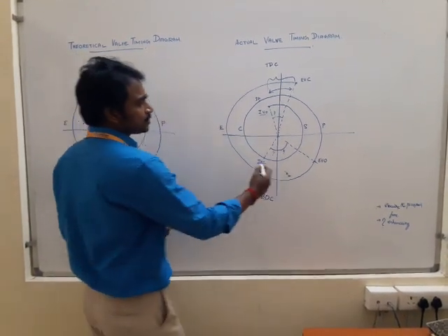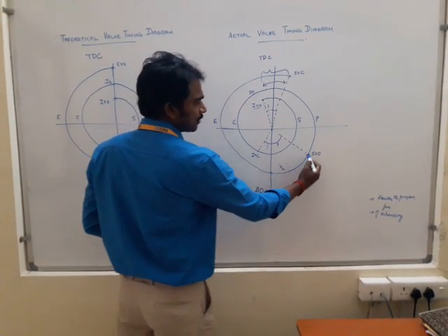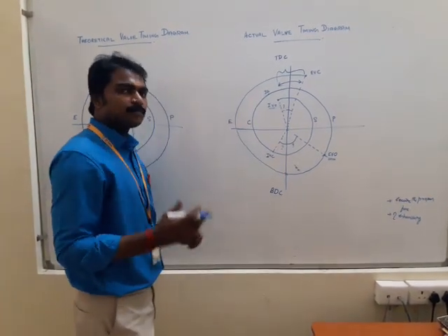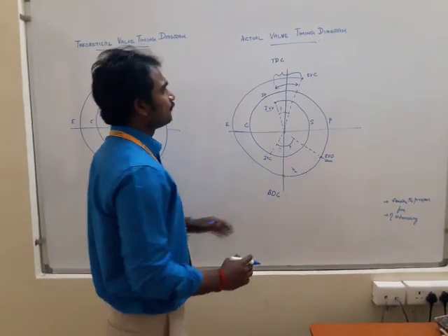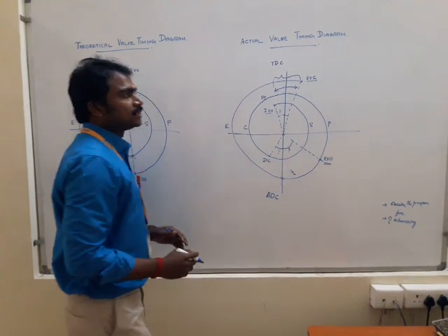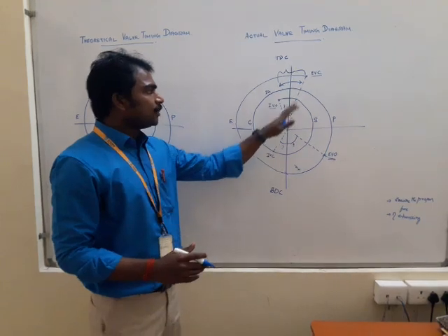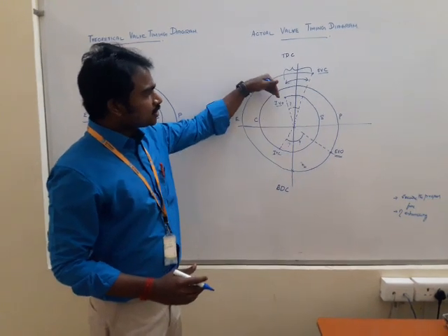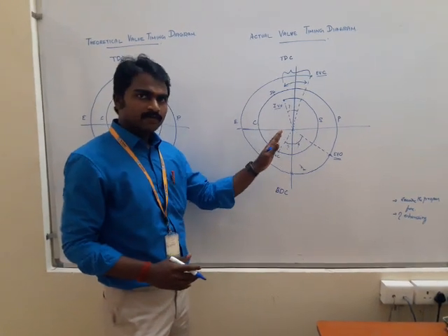Then the exhaust valve open, which is supposed to happen at this center, happens at this point, nearly 45 degrees before. Why? To reduce the pressure on the piston, the exhaust valve opens before BDC. Finally, the exhaust valve closes after TDC. This is to enhance the process called scavenging, through which the already burnt exhaust gases are removed from the engine by the entry of fresh air. So this is how the actual valve timing diagram works.